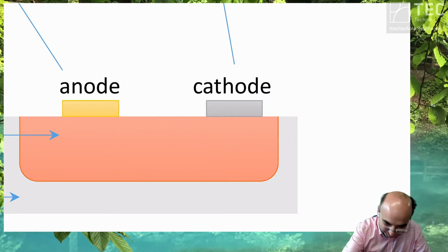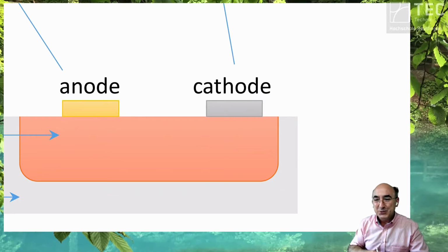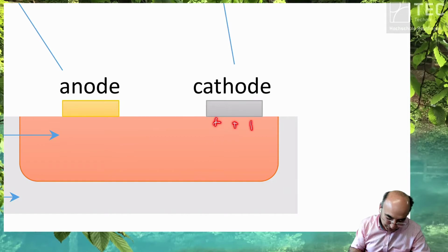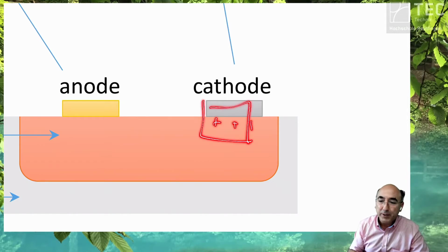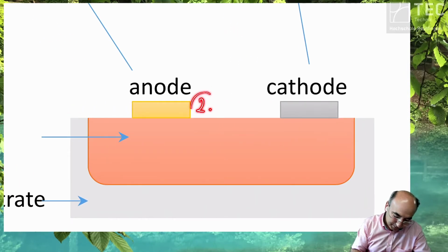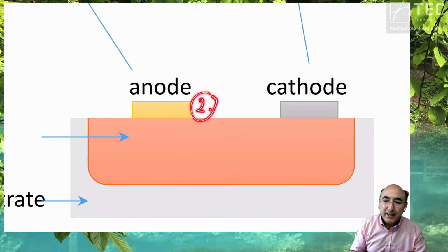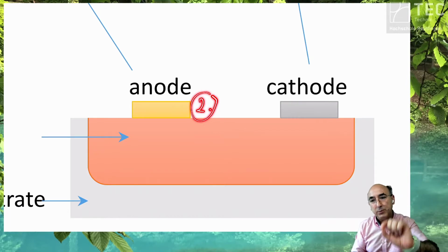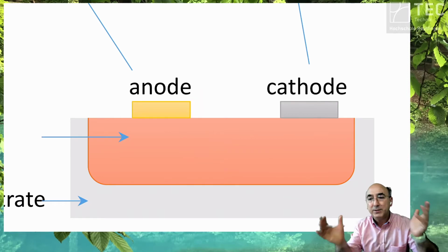Okay, so come back to degenerate doping. So this area is really ohmic due to the high doping level. Okay, but then you place the metal. And then you never heat up this wafer again to values, let's say, of some 100 degrees C.